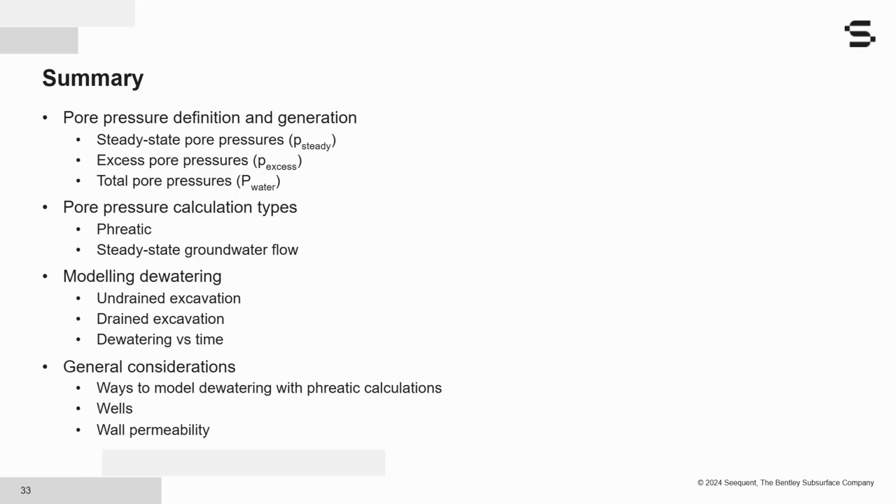But you need to also remember that you need to define in a steady state analysis also the flow boundary conditions. So you need to, like we said, go around your model, and then tell Plaxis what is closed, what is a flow, what is a seepage. So you need to be a bit more meticulous in how you define your boundary conditions.